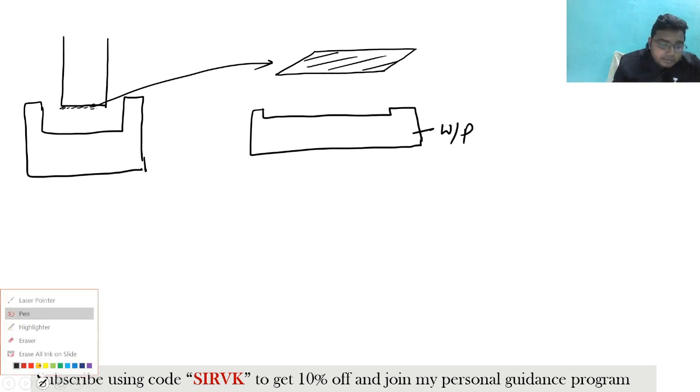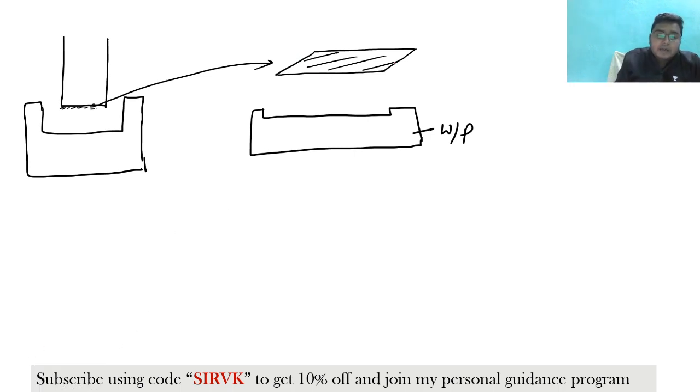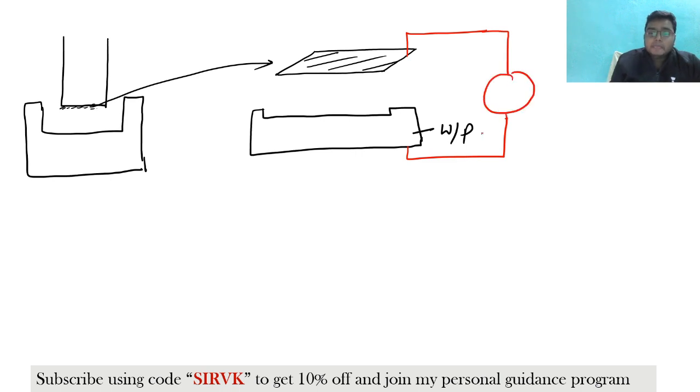Now, in between, what is happening when you have connected this workpiece and this tool with the power supply? This is connected with the negative terminal, and this is connected with the positive terminal. So the current will be flowing, isn't it? But there is a gap. Suppose this is denoted by the length L. So there is a gap between the tool and the workpiece. Due to this gap, there is an obstruction in the path of the current, right?